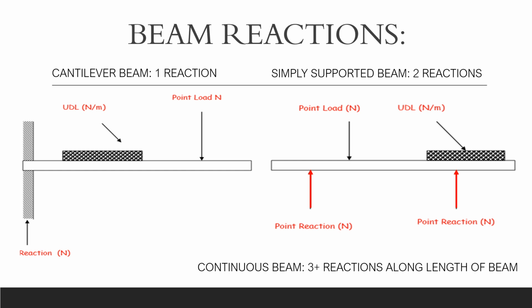So we've got all our point loads. I know you can see distributed loads here, but if you think about different types of beams, what we would need to calculate is the reactions. So the idea is you've got these loads pushing the beam down. So what's going to hold it up? Well, actually, you need to have an equal reactive force coming in the opposite direction. Otherwise, you would just be sinking, wouldn't you? The beam would just sink and keep going downwards if the columns holding it up were not strong enough. Yeah. So that's the concept here.